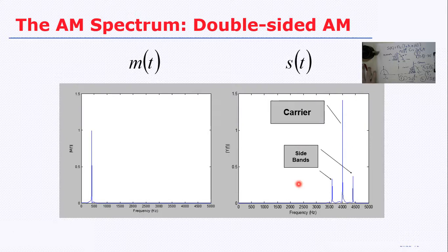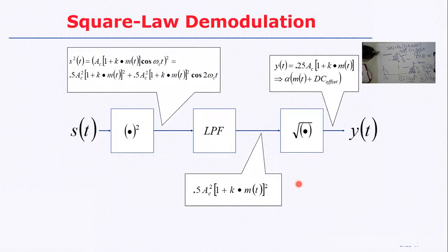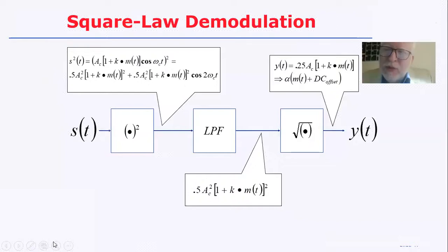Okay, that's perfect. So in the next lecture, or I'm sorry, the next part, I'm going to investigate more about the demodulation. Simply, if the modulation is the transformation from the baseband signal to a passband signal, the demodulation is simply the returning back from the passband signal to a baseband signal. So now you have the signal over the carrier, and you are seeking to return it back to that baseband format, to the original format. So this will be the topic for the next part.